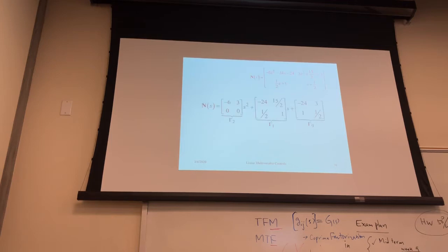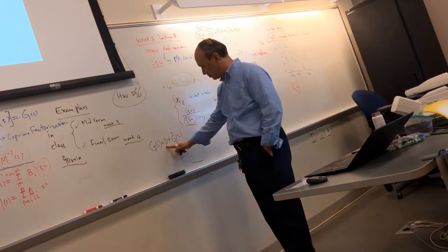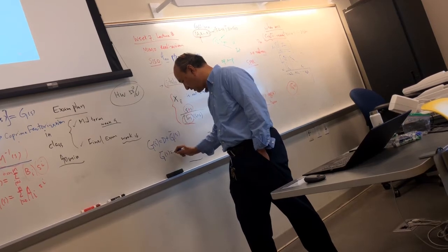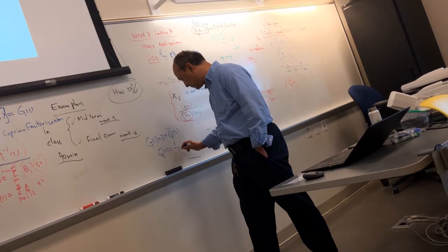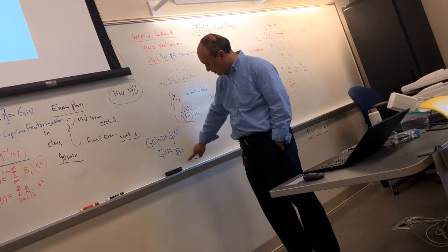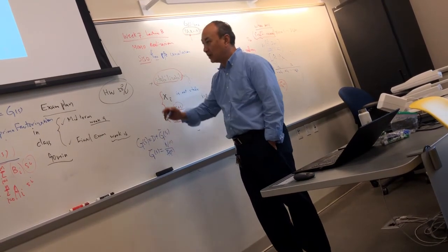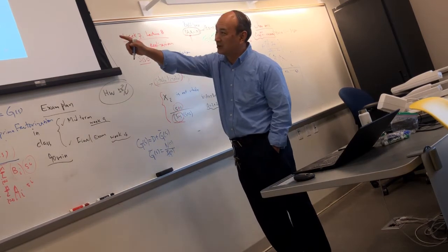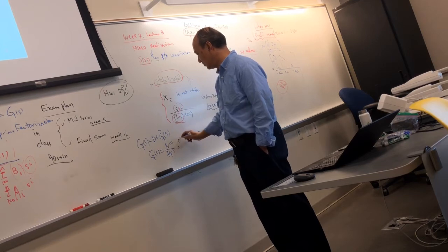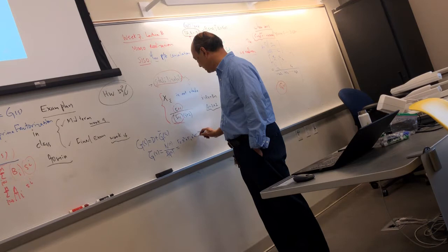So with that, you can express your original g of s as D plus g bar of s. This is the direct feedthrough term. Now I'm writing g bar of s as 1 divided by a capital D, dg of s. This is the characteristic polynomial, a determinant. And here you have a matrix transfer function, gamma 2 s squared plus gamma 1 s plus gamma 0.